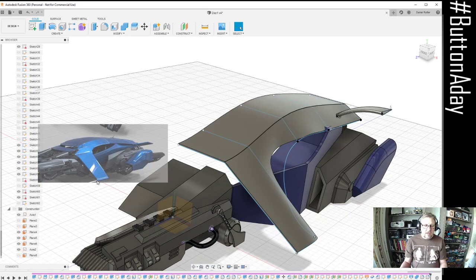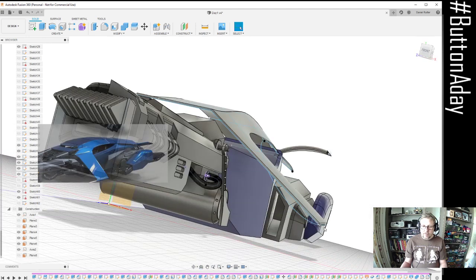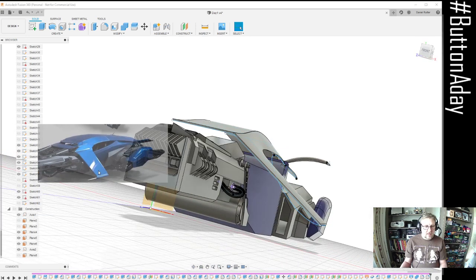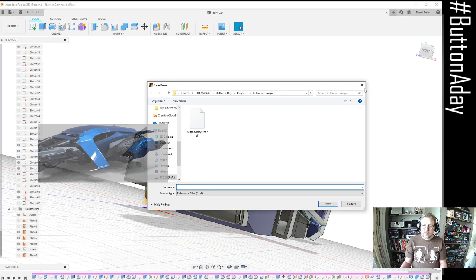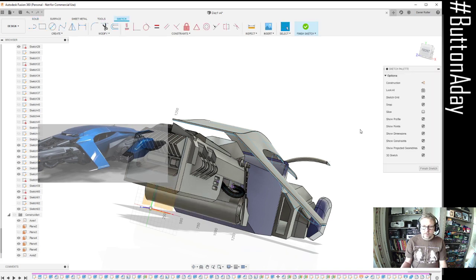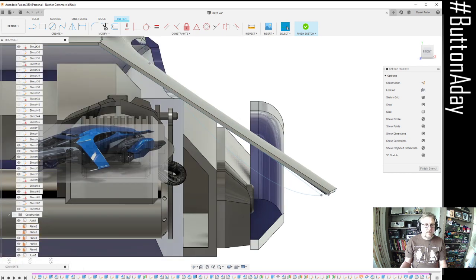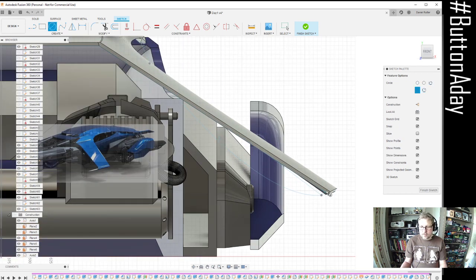I'm going to add just a little, actually we'll do it now, we'll add a little spike on that bottom part, because that looks kind of cool, that piece there. So let's create a sketch, do it on this front plane. I'm going to click on our view cube so we spin round to the front. Just going to draw in something like that, say 120.